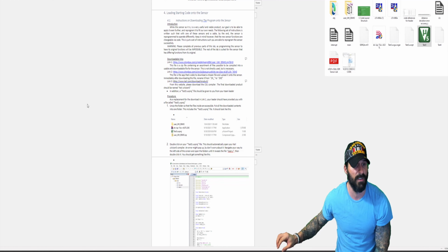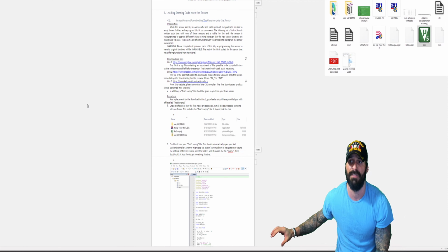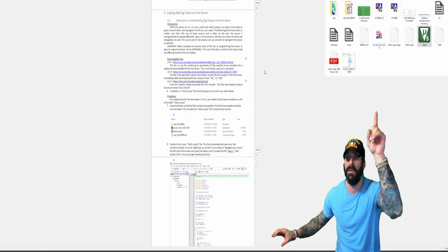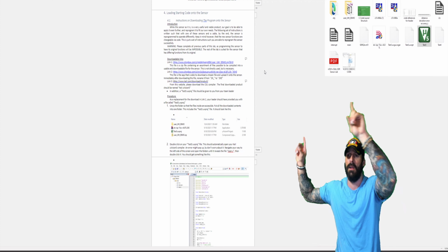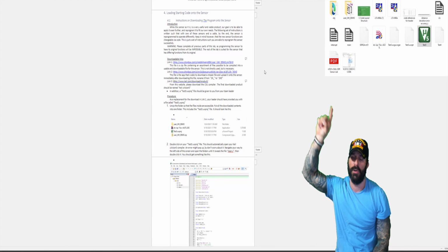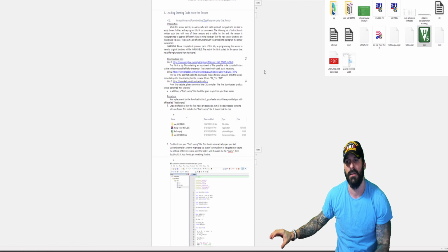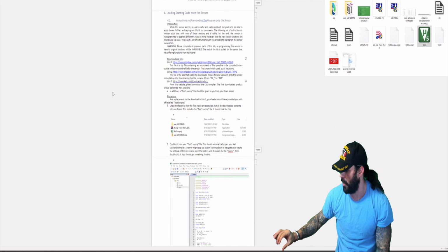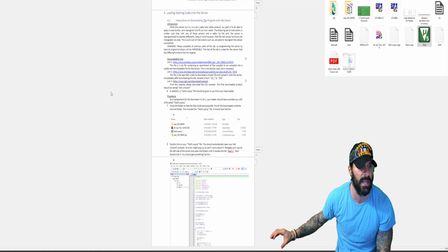So once we have everything there, you're going to click that rebuild button, and once you have that, if you look above me, you're going to see a few additional files: I2C, interrupt, and main. Above that you'll see the object folder. In that object folder is the hex file that you'll need to upload once we get to that part of the instructions, okay? So now that we've modified that code, you're going to see the I2C.lst, interrupt, and main.